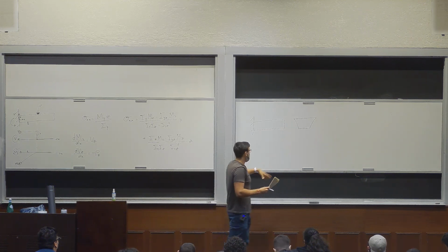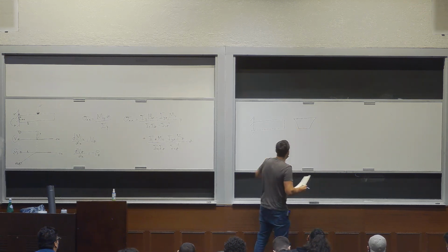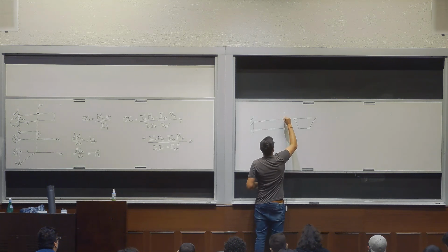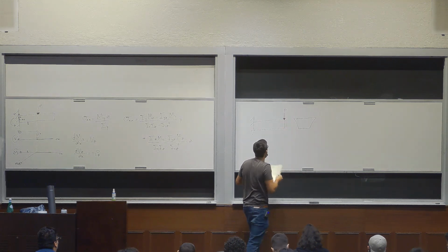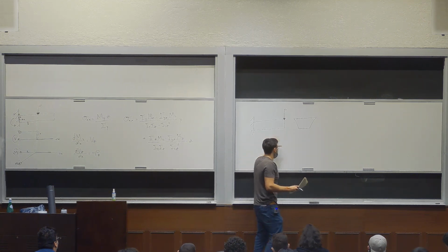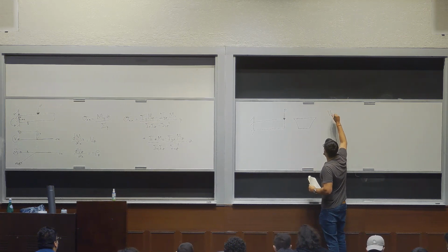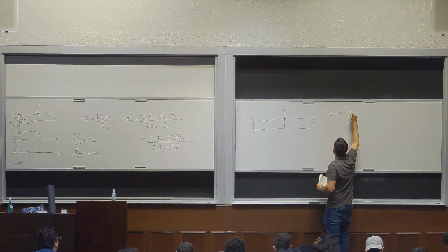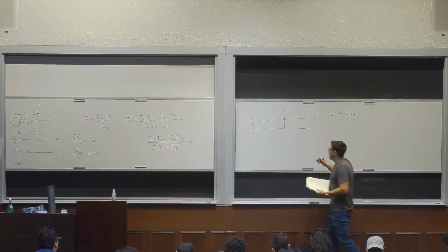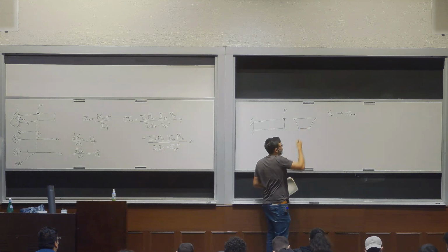It's not like concentrated areas or thin-walled sections. These are solid sections. If you have some applied P, you're going to have a distribution of this shear force across, where it's going to be constant in this case. But that constant shear force V, Vz, is going to produce some tau xz, some distribution of that across the cross section. We're interested in finding out how that tau xz varies from top to bottom.